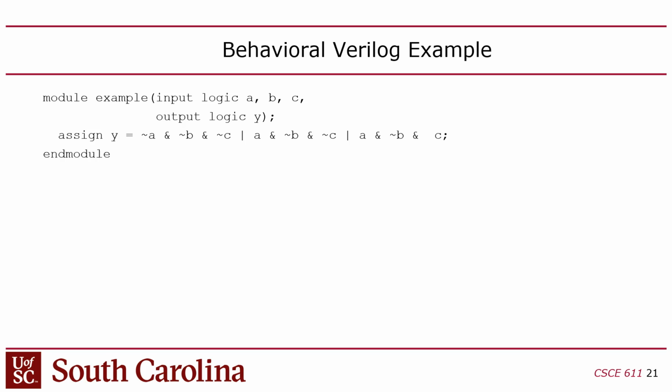One is that the first only supports Verilog and not SystemVerilog. And Verilator doesn't support the Z and X in logic types. It doesn't use what they call multi-state logic, which is the standard for Verilog. So if you use Verilator and you have a double-driven signal, there's no way to know.